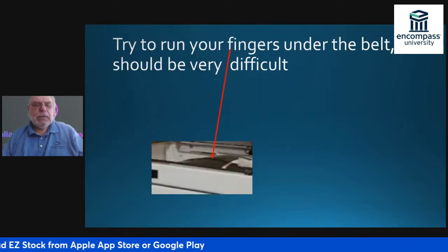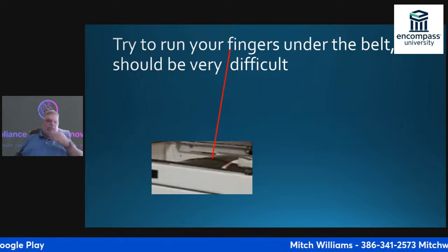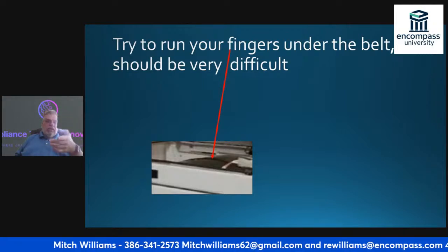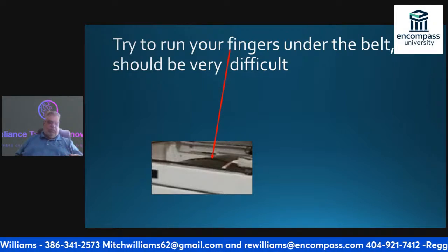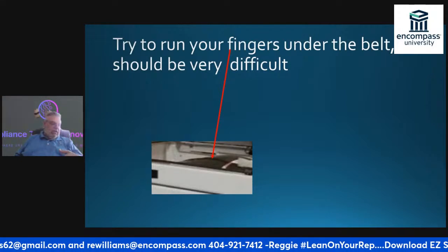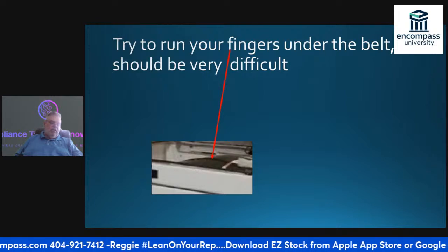Okay. So one of the other things that I need to do while I've got this up and I've checked the door switch, and the door switch checks out. The next thing I'm going to do is try to stick my finger under the belt and see if I can get my finger up under it. It should be very difficult for me to do that.